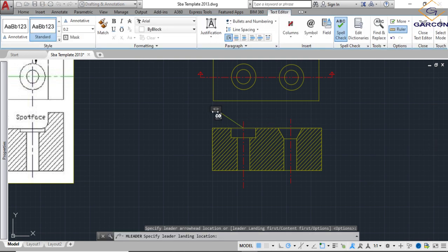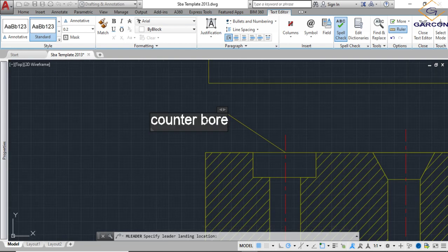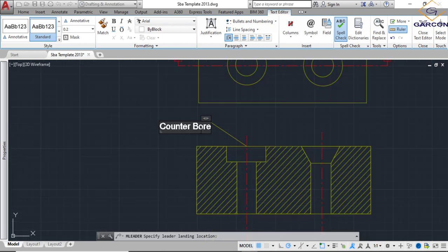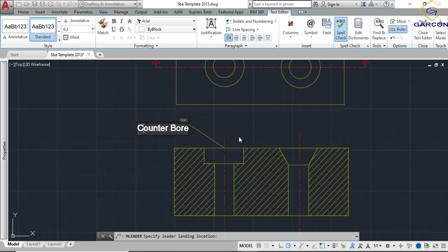Call this counterbore. Counterbore is basically where you use a drill bit to bore the hole before you enter the screw, so the screw head goes down into the material. While countersink is using the screw itself. Countersink comes from the property of a screw to find its way down into the material and flush itself into the material. So you'll use a drill bit to make this one, and this one you allow the top of the screw to make its way down into the material.